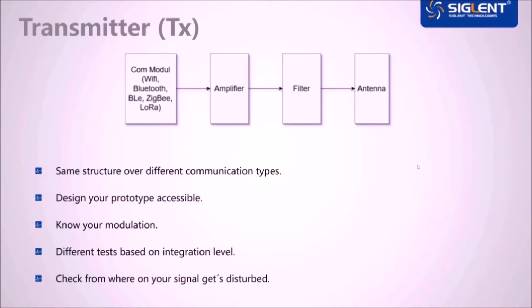When you're developing such a product, try to make as many test points as possible accessible, at least within the prototype. For example, you can create a second PCB with your antenna design or an optional SMA connector on a trace between two components. The goal is, of course, to be able to capture as many signals at as many points as possible.